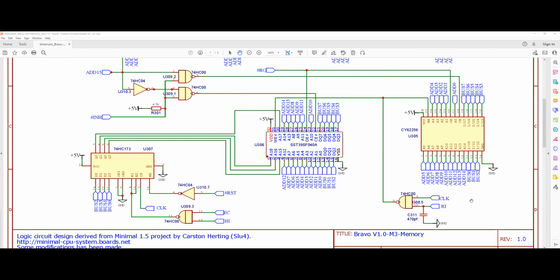So whenever we want to write something to the chip from our bus, we just bring the RAM in signal high, and essentially on the next valid clock cycle, the output of this NAND gate will be low, and the write operation is going to happen, and that value will be saved to our memory chip at that specific address. All right, so this is about the write operation.